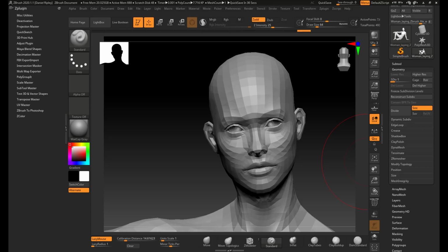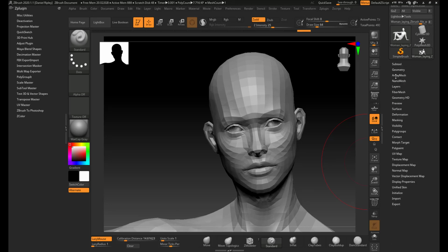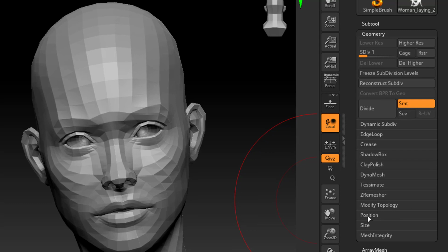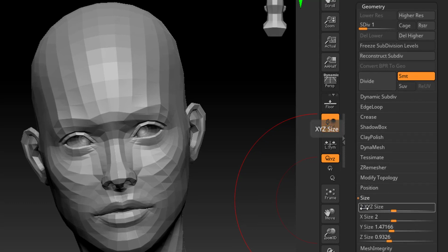You can normally tell whether the scale's right for Zbrush because when you go into your, not your subtool, but your geometry, you open up the size, and the size should be roughly 2.000 something. If it's showing that, then it means that you're working within the tolerance of the way that Zbrush works best. This normally means you can create displacement maps straight away without any problems.